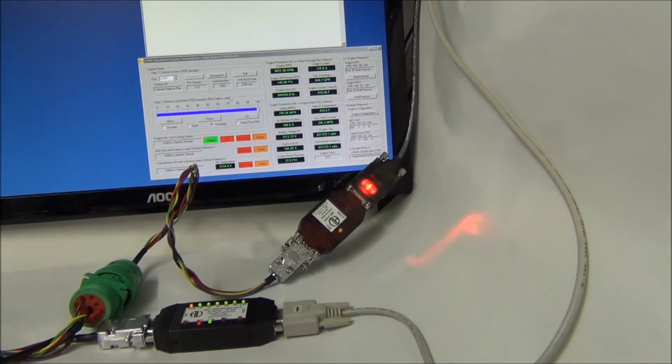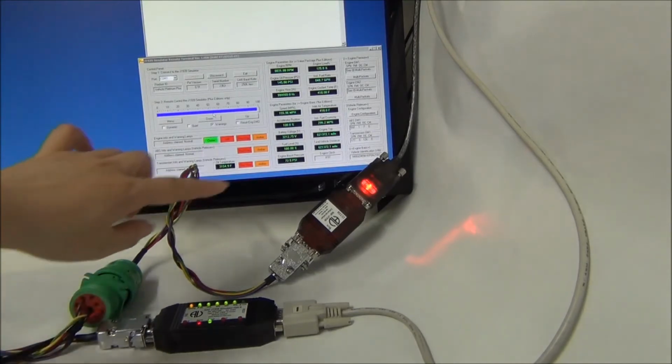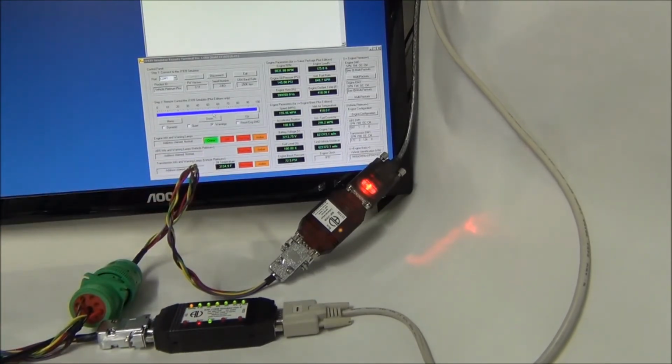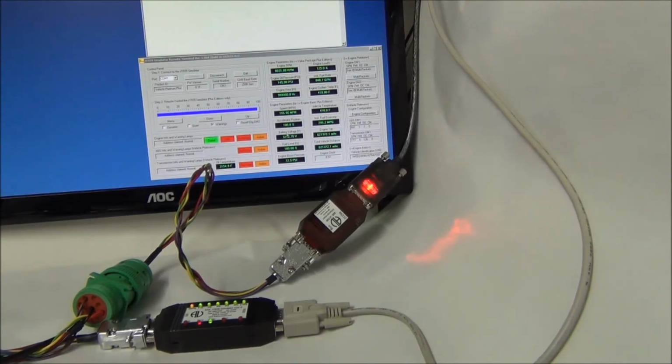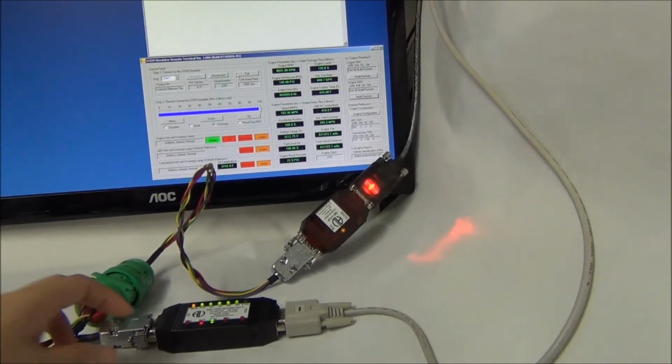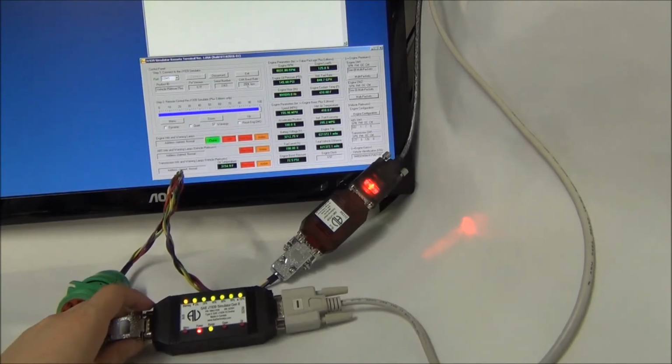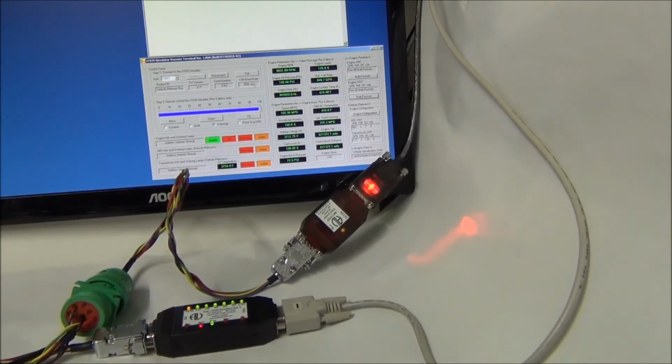Now I'm going to demonstrate how to use the remote terminal GUI to change or configure the CAN bus baud rate. In this CAN bus network, we are using another device called an AU J1939 interpreter. It is set up at 500K CAN baud rate. And from the GUI, we can see this simulator's CAN baud rate is 250K. Because they are talking at different baud rates, you won't be able to see any data flow on Tera Term.